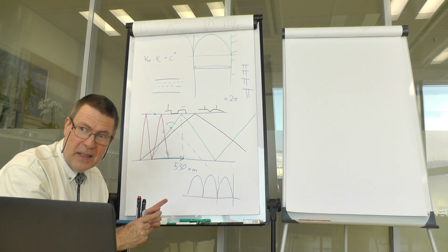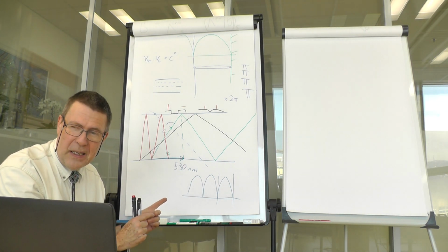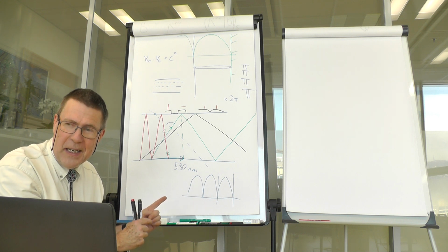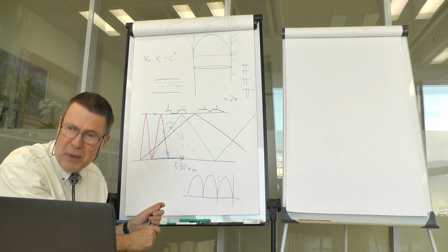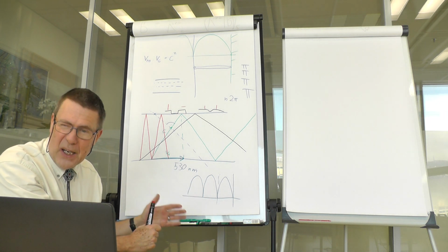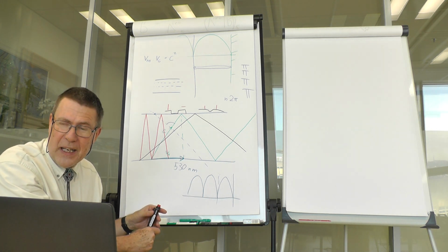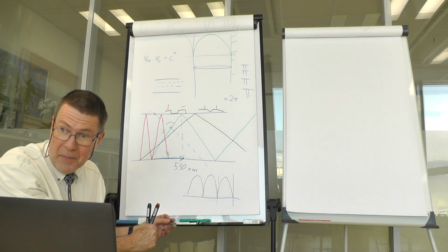We haven't been faced with this problem with a transmission line like a coaxial cable. At least in a lossless case, it has no dispersion, and it can carry a signal which even starts at DC.